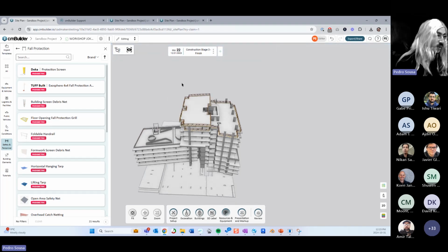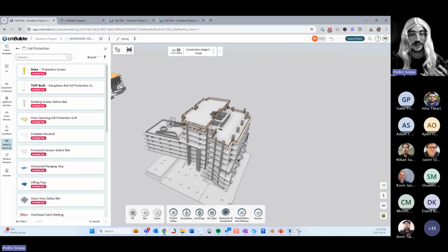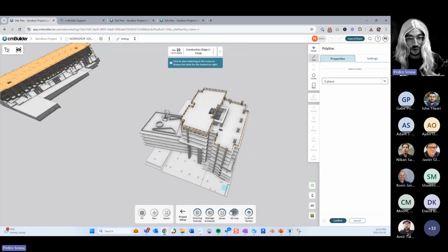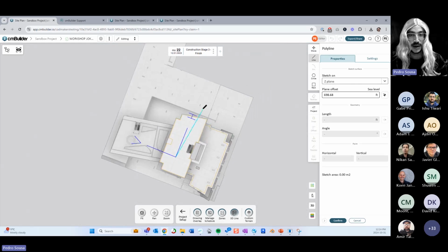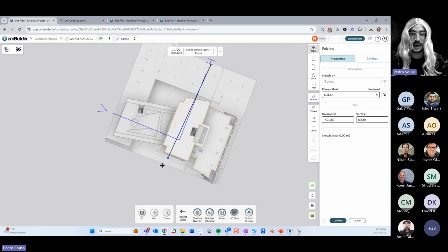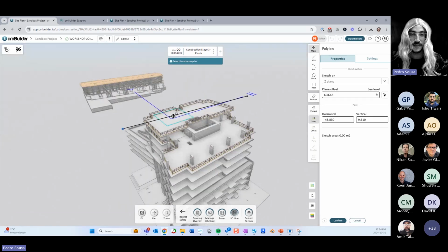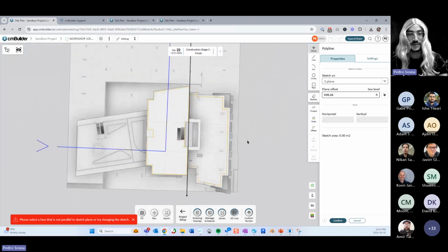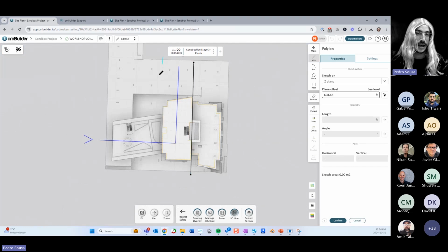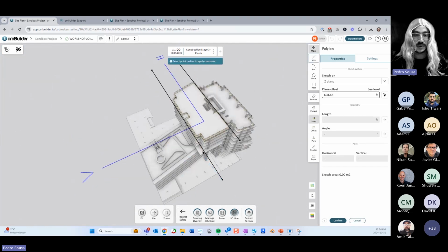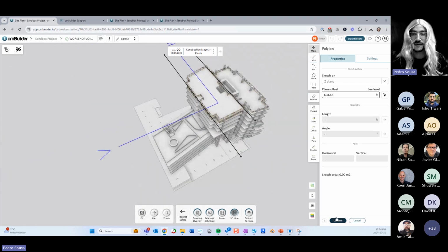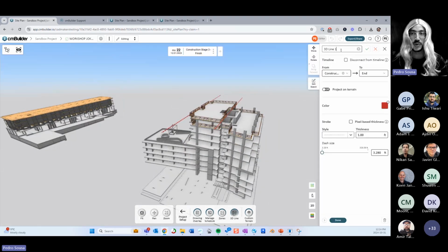So until we post that, one thing that I would suggest is for you to create a template of your splits using a normal 3D line. So you create, let's say, a template that you're going to split this way, the same way that I did before over there. So I can snap this to this face, and let's say that's going to be my template for this split, but I also want to create a template for the amenity levels. I can do the same thing over here and snap this. And I have these 3D lines. Their name should be like a template split, right?